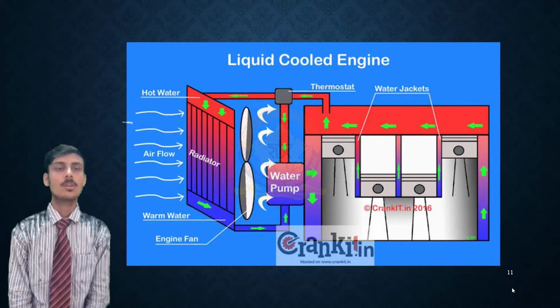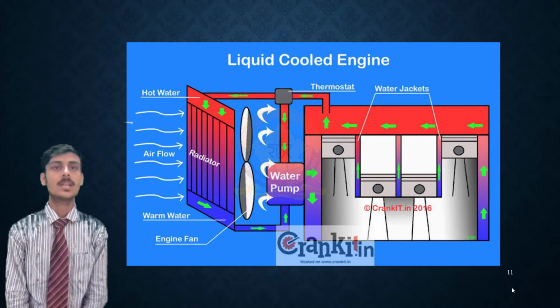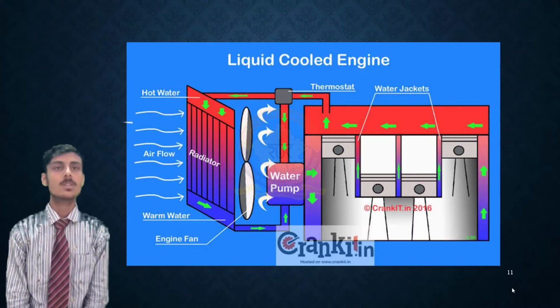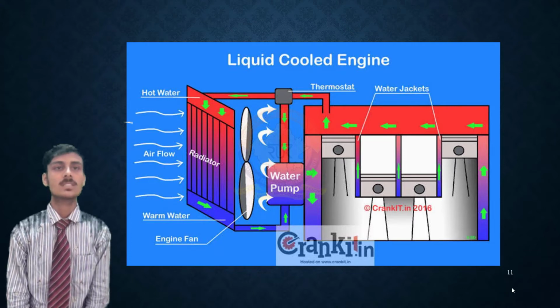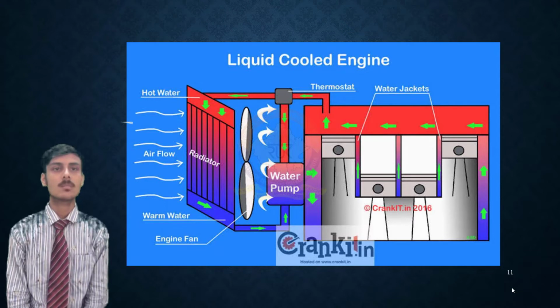Under pressure, the boiling point of the coolant is raised considerably. However, too much pressure will cause hoses and other parts to burst. So, a system is needed to relieve pressure if it exceeds a certain point. The job of maintaining the pressure in the cooling system belongs to the radiator cap. It is designed to relieve pressure if it reaches the specified upper limit.